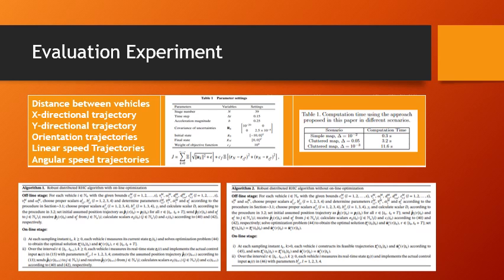Because algorithm 2 is an adaptation of algorithm 1, substituting the optimal solution with feasible trajectories constructed recursively, the recursive feasibility of optimal control, robust admissibility of desired constraints, collision avoidance between multiple vehicles, and robust convergence of tracking and formation can be guaranteed by applying either algorithm 1 or algorithm 2. If they are guaranteed by trajectories constructed for the graphs of orientation, linear speed, and angular trajectories, we can say the deviation evolved and solved the nominal trajectories, which are larger than the feasible trajectories, giving more freedom to the online optimization present in the algorithm.